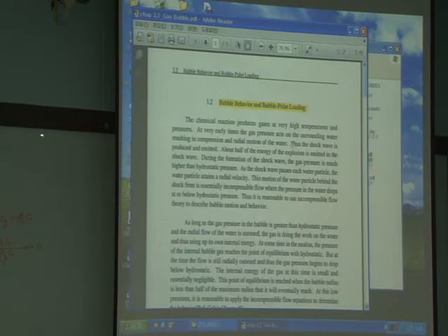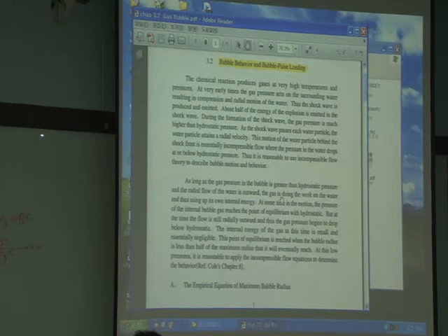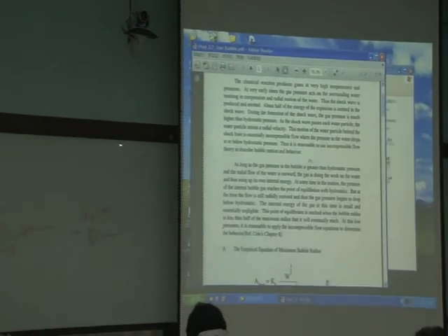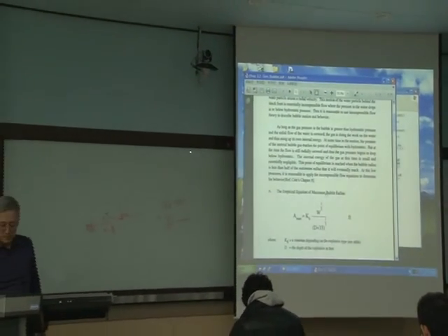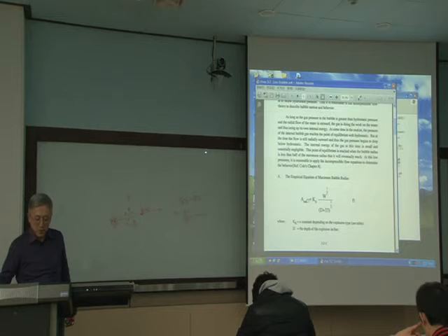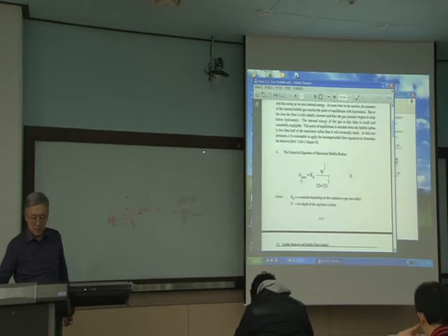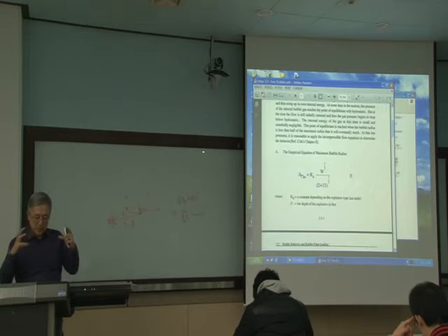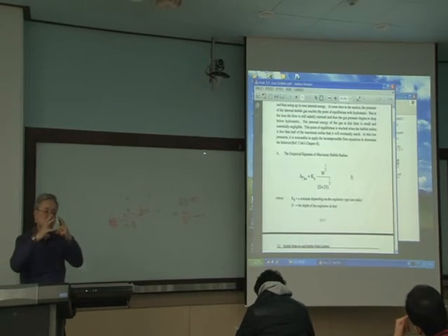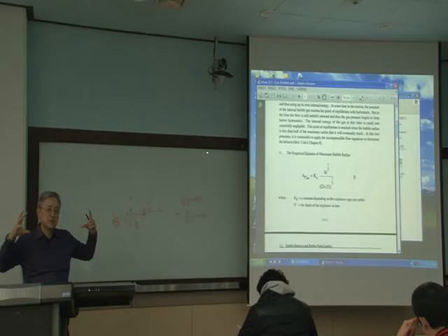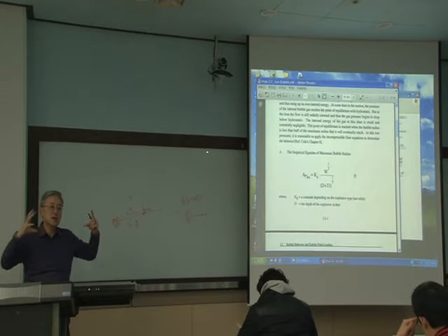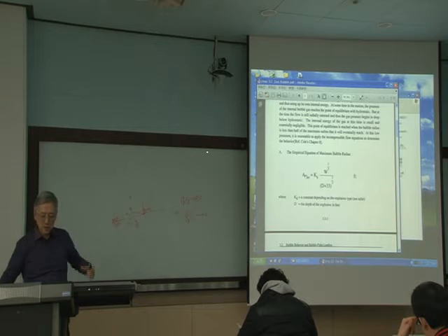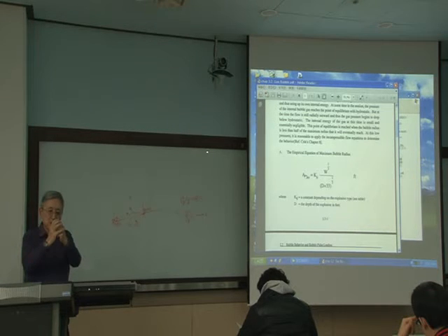And please read all this. It's nice, I summarized all this, you can read. This is an empirical equation for A max, the maximum gas bubble size, the initial gas bubble size, which has the highest energy trapped in there. So after that it shrinks down to min, collapses, and gets back out.